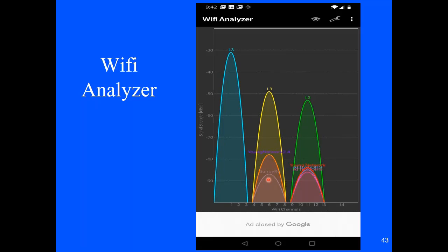I actually had a test application where one of our customers had some transformers outdoors, and they wanted to know if they could use their existing Wi-Fi, and we could set up some Wi-Fi meters, because I've got some meters that'll accept Wi-Fi. So I pulled this little program out, saw we had about 65 decibels, and told them it'd be good if we could get another Wi-Fi transmitter closer to those transformers outdoors. So this is a great tool you can use to analyze your Wi-Fi network.